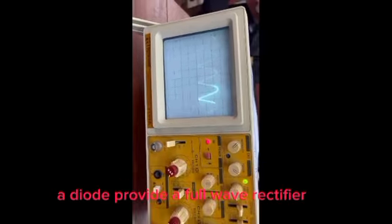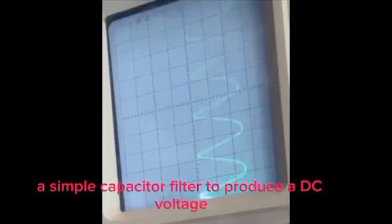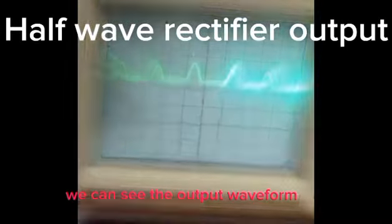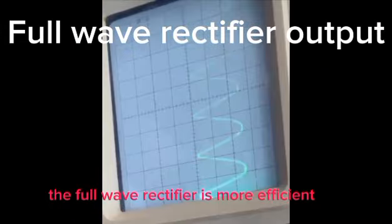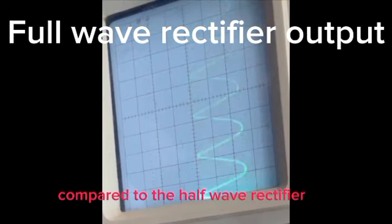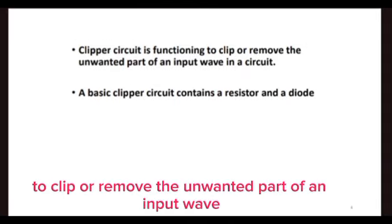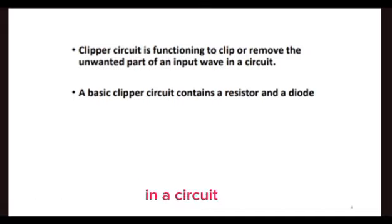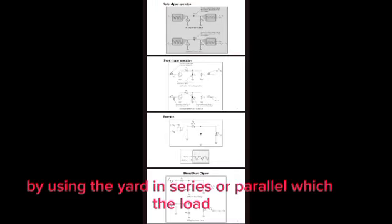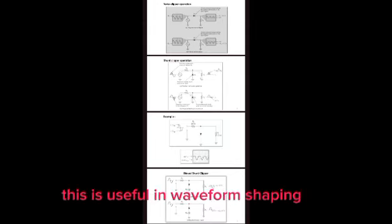A diode provides a full-wave rectified voltage that is initially filtered by a simple capacitor filter to produce a DC voltage. We can see the output waveform. The full-wave rectifier is more efficient and provides smoother DC output compared to the half-wave rectifier. The clipper circuit functions to clip or remove the unwanted part of an input wave in a circuit. By using a diode in series or parallel with the load, we can clip the voltage peak. This is useful in waveform shaping and signal protection.